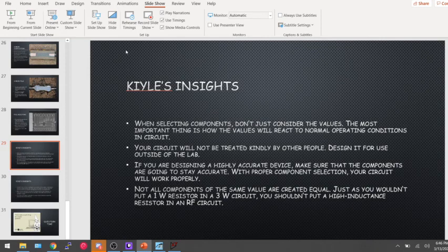To give you an example, the Allen-Bradley resistors are much better sealed than the other kind that I showed you. The reason that their values drift is because the moisture at the seal is really important on that. So you have to also take into account how they're constructed. Like that other capacitor that I showed you earlier. Not all components of the same value are created equal.